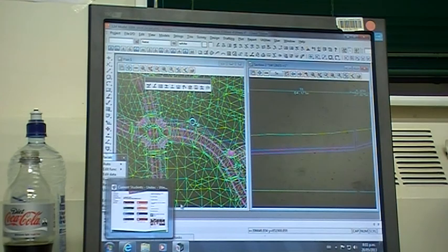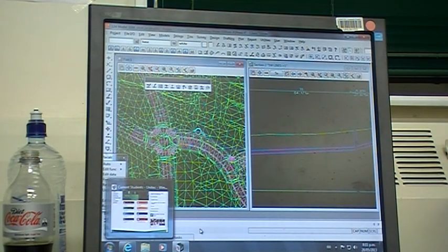Does 12D have trenchless pipe calculations? Well, essentially, it's the same calculation. You're still working on its capacity based on the smoothness of the pipe, the grade of the pipe, and how much water is going to go into it. So how it gets in the ground really doesn't come into the thinking of the design engine.